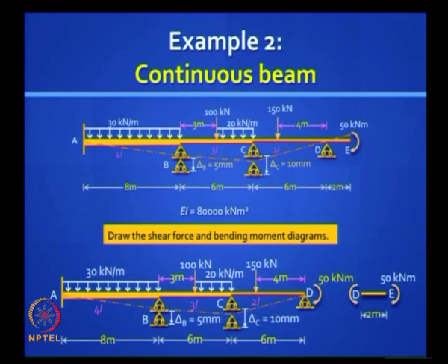Okay, now tell me, we have got a reduced problem now, just a 3 span continuous beam. What is the degree of kinematic indeterminacy in this? It is just 2 if you want to take advantage of the hinge at D, right. So from 5 it is a massive plunge to 2. So that is a clever thing and we should do it correctly without making any mistakes. So please pay attention. By the way, we did this in slope deflection method. We did this in moment distribution method. We will now do it in matrix method.